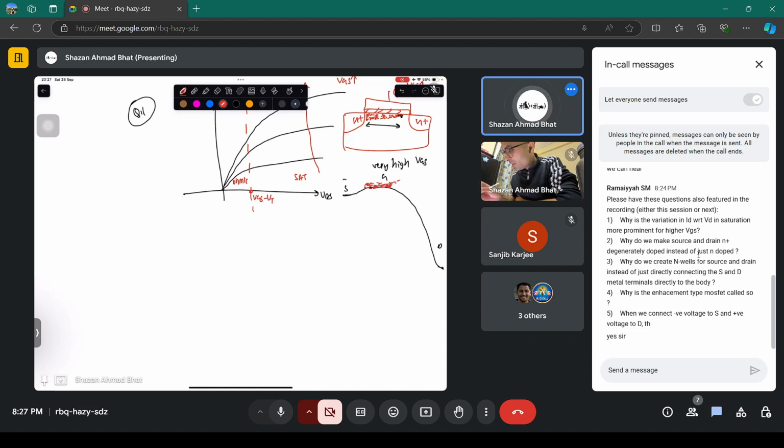So many electrons here. Some of the electrons at this particular position just rush down to the drain side because of the drift present, because of the huge drift, I should say. When does the pinch off occur? Pinch off occurs at very high drain to source voltage. Okay, so when the channel is pinched off, you have now more electrons.